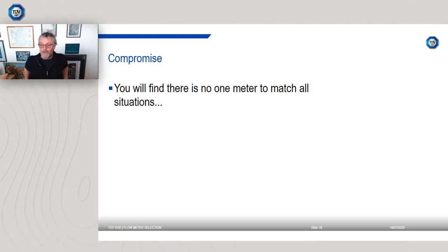If I've got to measure, for example, let's say between 300 litres per minute and 400 litres per minute of pure pentane, and it's a process that's very tightly controlled, and I want to measure the mass flow of that pentane. Just an example, or the pentane could be water. Well, a single Coriolis meter will do that, to a very, very low uncertainty.